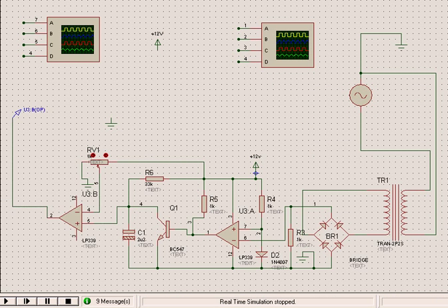And then we go over to one more operational amplifier in the comparator mode. So that sawtooth voltage is taken here and then again compared with a variable voltage. This voltage in fact will be coming from some output feedback. So this voltage will be varying, and we'll see while varying this voltage how the output is affected. And this output we have taken